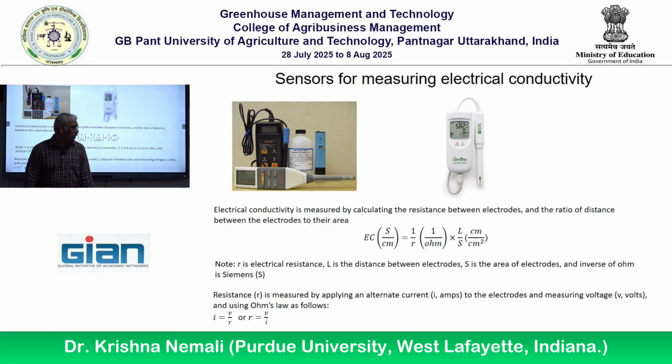You have to keep in mind that all these EC sensors are affected by temperature. The measurement that you get, whatever the calibration that you're looking at, all that resistance calculations and the output voltage, that is highly sensitive to the temperature. Usually it is done around 20 or 25 degrees Celsius at the manufacturer site, okay?